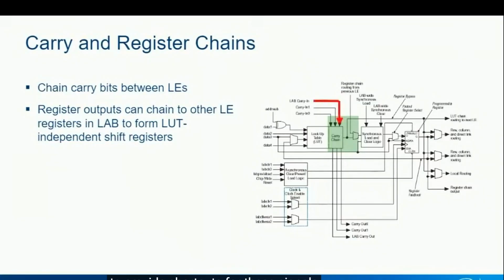Carry bits can come from other LEs within the lab or from other labs in the device. Generated carry bits can be outputted to LEs or to the device interconnect. The LUT and carry logic can be bypassed completely within the lab to chain all the LE registers in the lab, turning them into a shift register, perfect for DSP type operations. The versatility of the carry logic and register chaining routes provides further performance and resource management gains over CPLDs.